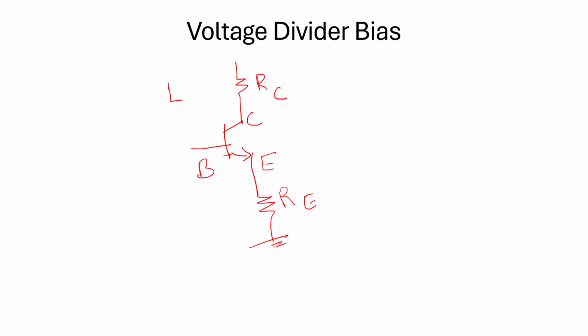In order to have a voltage divider, a simple potentiometric setup is connected to the base region. Now we have formed a voltage divider. This voltage divider section is connected to our transistor in this way, right? So let us name this as R1, R2, where R1, R2 will be behaving as the voltage divider resistors.